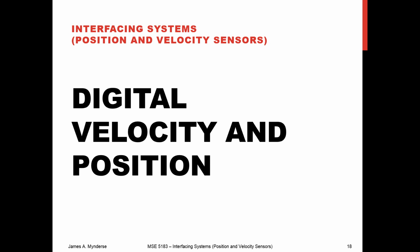So last time we were talking about analog position and velocity sensors. We talked about potentiometers and LVDT and Hall effect sensors, and then we also talked about tachometers for velocity. And remember, one of the problems with a tachometer was that because it's an analog system, there's noise on it, and we don't necessarily know when the tach is reading zero speed or whether it's reading noise or a slow speed. So one of the ways we can get around that is by using a digital sensor.